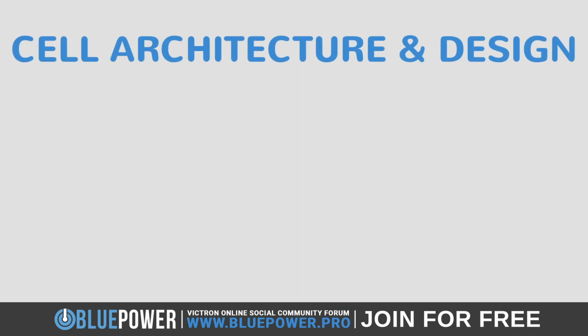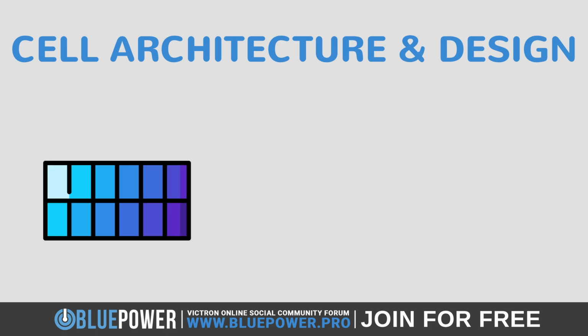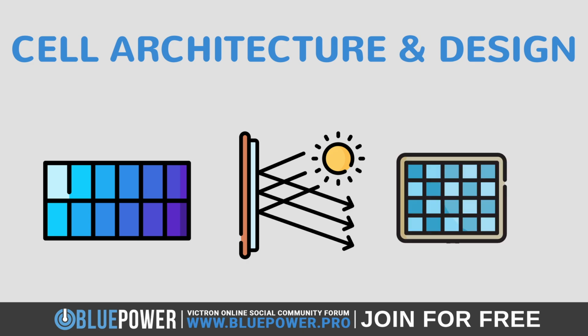While the material of a cell heavily impacts its efficiency, its design is also very important. For example, texturing the surface of the cell reduces reflection and increases the absorption of light. Coupled with this, anti-reflective coatings minimize the reflection of sunlight, allowing more light to enter the cell. Then, the passivation layers in solar cells reduce the recombination of electrons and holes, minimizing potential electric current loss. This allows more electrons and holes to contribute to the electric current, thereby increasing the overall efficiency of the solar cell.